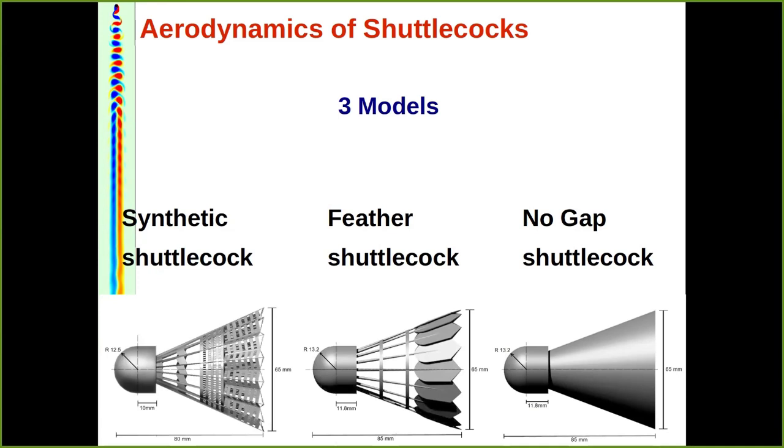Okay. Actually, this one has the least drag. And it was so counterintuitive. I thought this is a bluff body and it should have the highest drag. And that's the beauty of a shuttlecock. The gaps actually are very important. They are the ones which lead to drag.